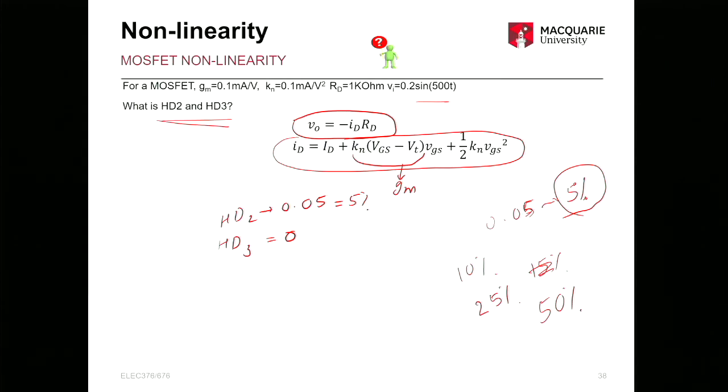Diode, you can, just like you did. So it's like RD and a voltage source with VD. Once you have that DC operating point, then you can replace the diode with a resistor. Once you have the DC. Oh, I get it. This is done. And the voltage across the resistor is VD.